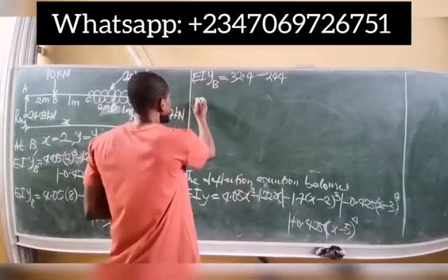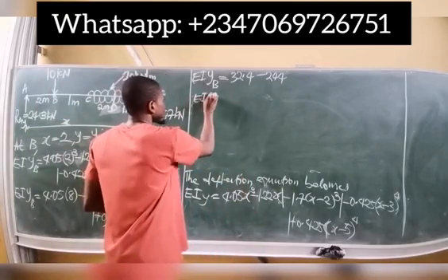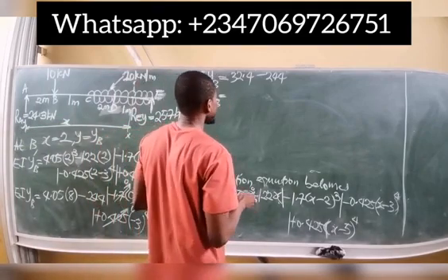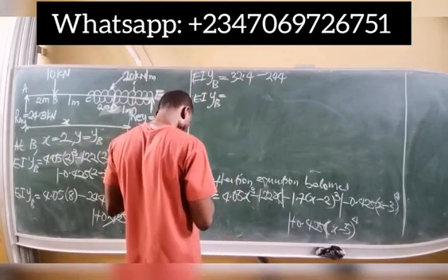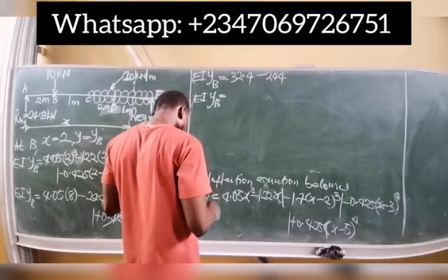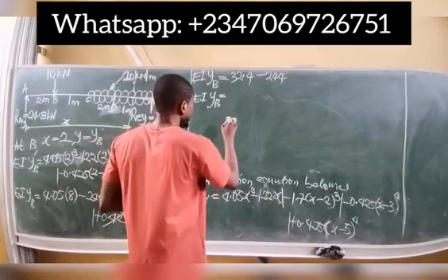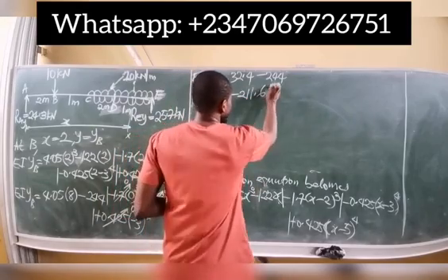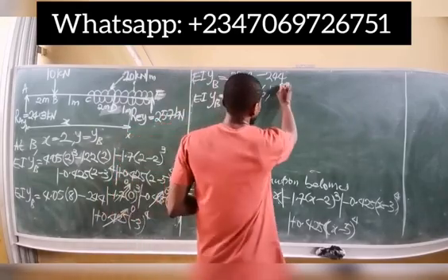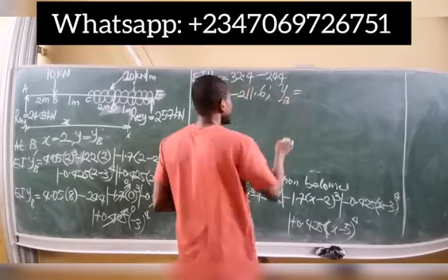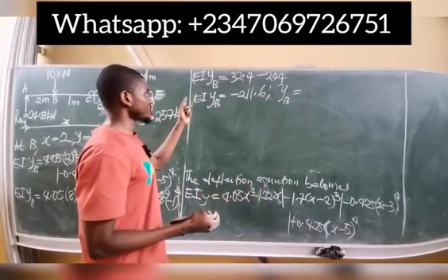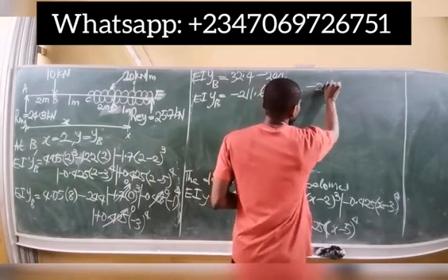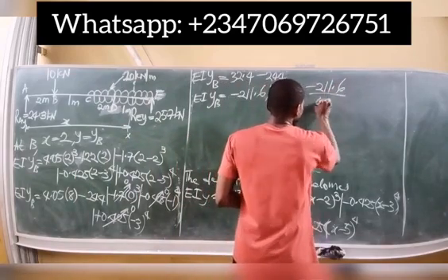So EIYB is now equal to 32.4 minus 244. That gives us minus 211.6. And therefore, you can make deflection at B the subject by simply dividing through by flexural rigidity, which is EI. So you simply have minus 211.6 all over EI.